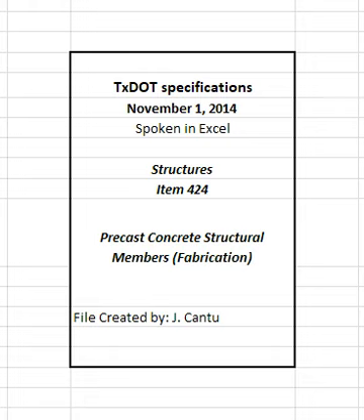Construct and maintain the soffit liner to provide a maximum 1/4 inches variation from the theoretical plane, and do not allow the soffit to vary more than 1/4 inches between any 2 points in any 50 feet length. At the contractor's option, construct side forms for bridge deck panels and prestressed piling with a draft for ease of product removal. Maintain product dimensional tolerances per Table 3. A maximum 1/4 inches draft is allowed for bridge deck panels.